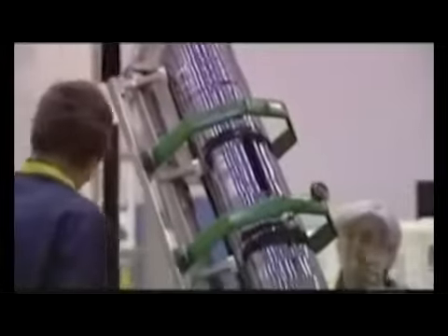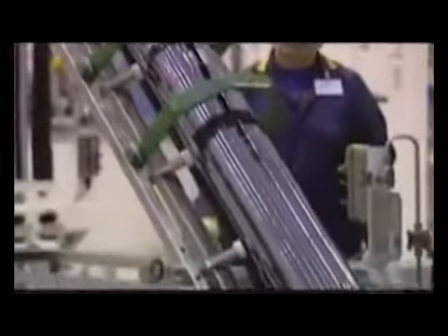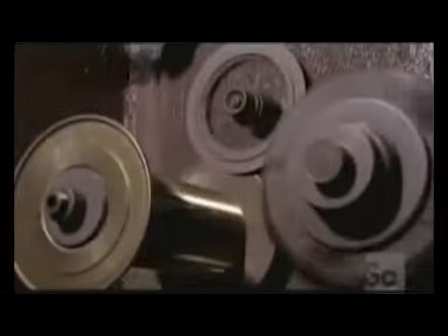But it is brittle, and it must now be cut down to size without shattering. After testing with chemicals and X-rays to check its purity and molecular orientation, it's fed to a silicon salami slicer. This 10-ton wire saw uses a fast-moving web of ultra-thin wire to produce wafers of silicon that are just 2/3 of a millimeter thick and 99.999% pure.